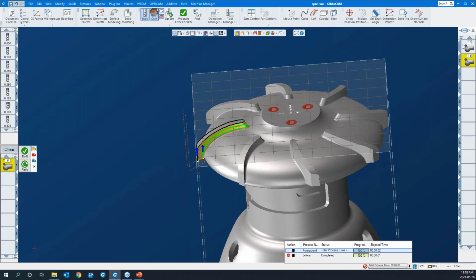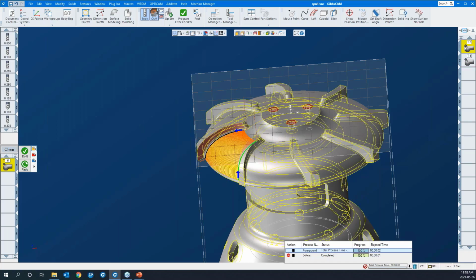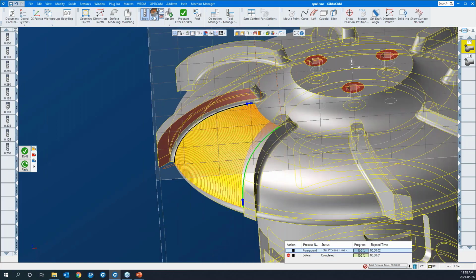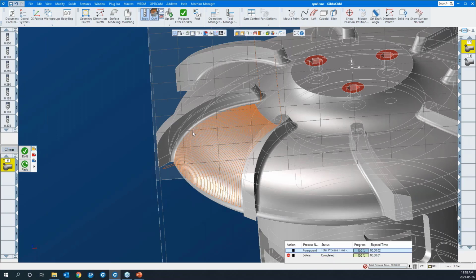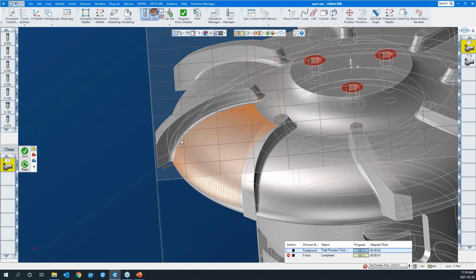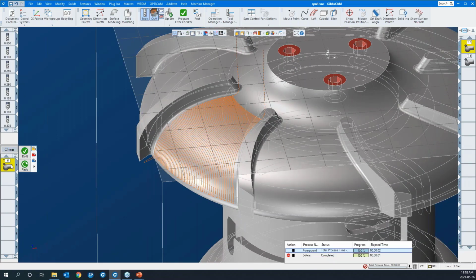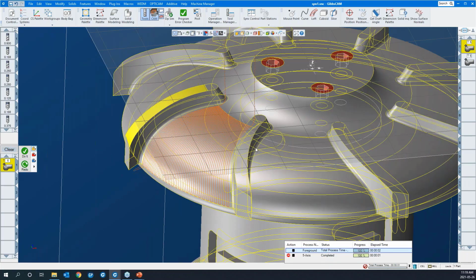Okay, let's go back to Op1. We were saying that it's a full 5-axis strategy, absolutely no problem. But you can also lock a rotary axis or lock 2. So let's look at reusing the data that we did for Op1 to cut the top of the blades.